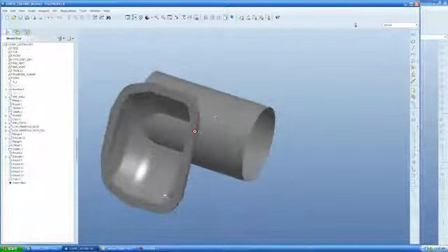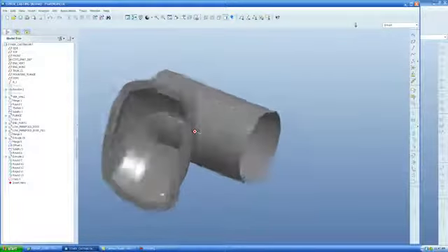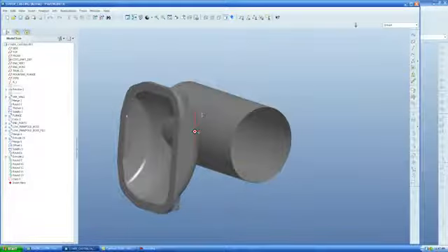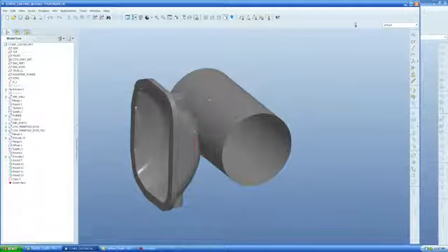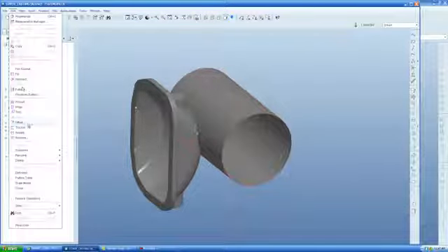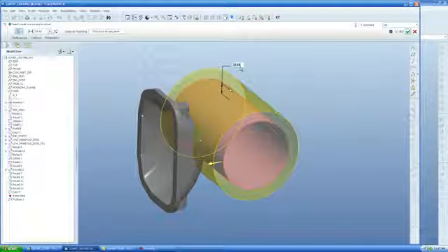So you're probably saying, well, how do we add material using surfaces? Well, this is pretty simple. Basically, I know my wall thickness is 18 millimeters, so I'm going to add the inside material first. So I'm going to select the surfaces that I copied. I'm going to go to Edit, Offset, and I'm going to offset the amount of material that I need.